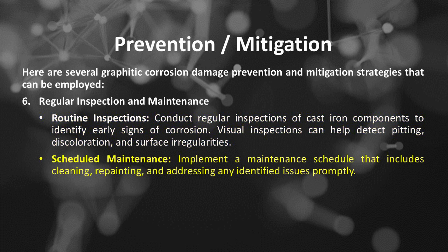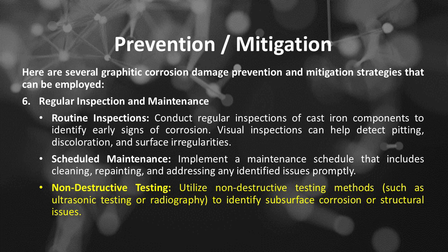Scheduled maintenance. Implement a maintenance schedule that includes cleaning, repainting, and addressing any identified issues promptly. Non-destructive testing. Utilize non-destructive testing methods, such as ultrasonic testing or radiography, to identify subsurface corrosion or structural issues.